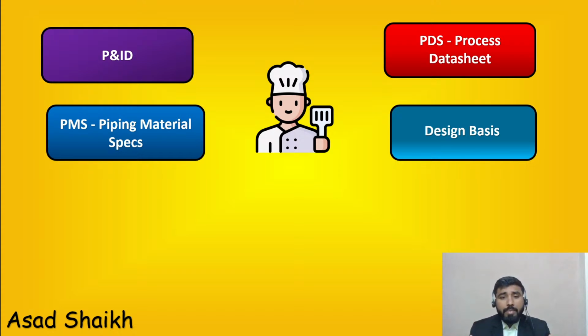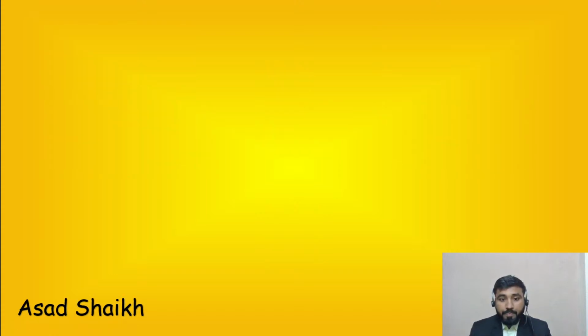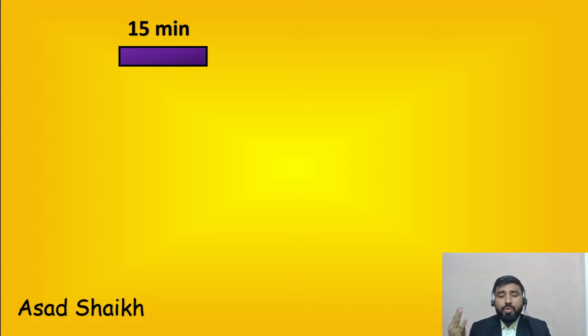A lot of the time, especially with process data, you might get something which is too much over specified, or it comes from hydraulic calculations but is not yet checked by the process engineer, especially when you do control valve calculations. So the first thing in making a data sheet is to ensure accuracy of all of these documents. Once that is done, you can move to prepare your amazing meal that is going to have a good final output. That being said, we'll try to divide the webinar into four sections.